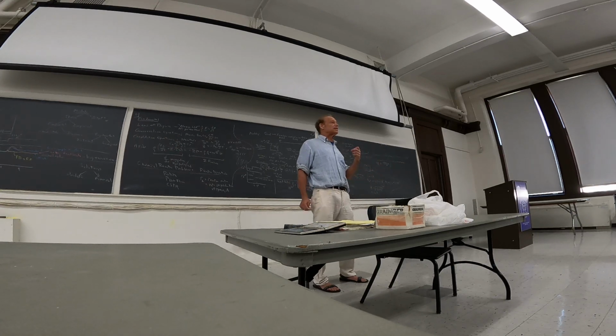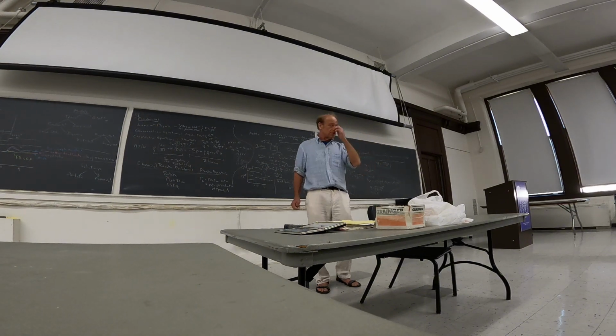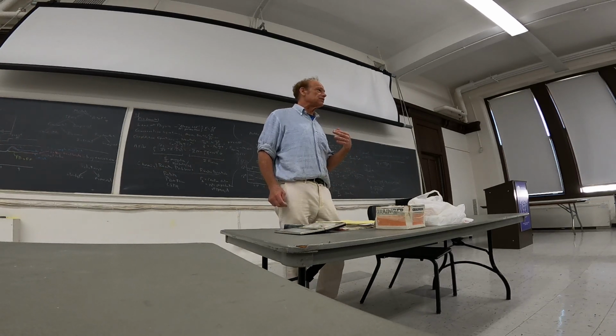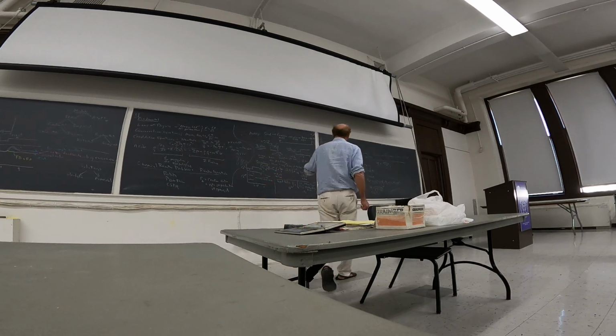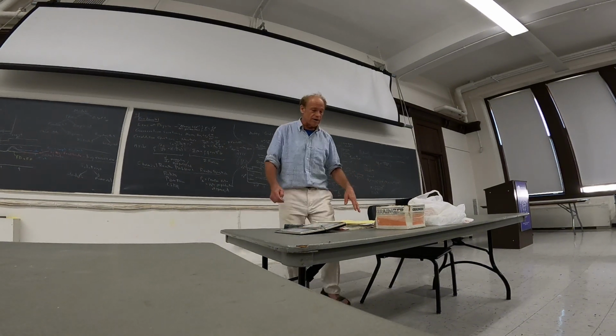So rather than think of residence time, think of space-time. It's the amount of time it takes to replace one reactor volume with fluid by flow. Again, that coincides with residence time in special cases, but if I have a non-constant density system, it does not coincide. It turns out this is the important concept, the appropriate concept, not residence time.